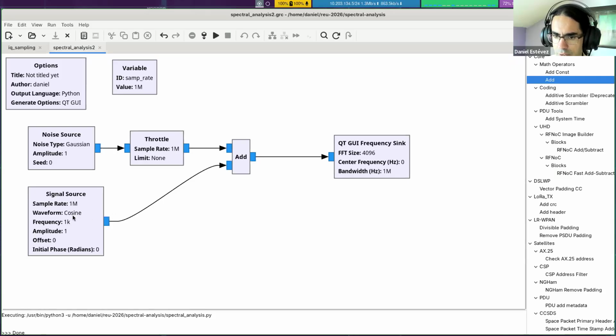So this is not going to run faster than this because it is limited by the addition, because we need to pair samples up. These ones are already limited at 1 megasample per second, so these will get limited because of the addition. So you can put the throttle block pretty much anywhere you want in one of the sources you have. You can put it next to one of the outputs. You can put it where you have combined everything. It doesn't really matter.